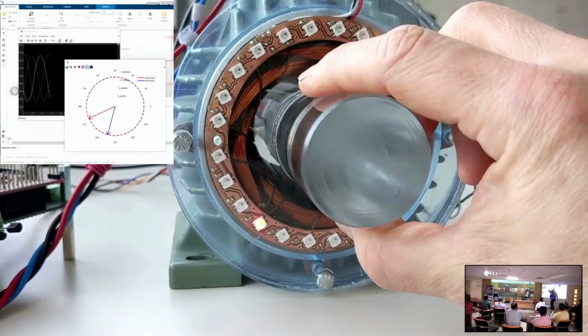This angle should not become more than 90. Usually it should be small. Then only P is equal to EV by XS sin delta. Sin 90. So when delta is 90 degrees, the torque, that is the power, is maximum. Maximum power. If it is beyond 90, it is the instability region. That is the observation here.